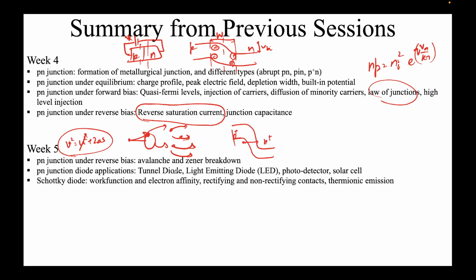And a similar application was the tunnel diode, whose I-V characteristics used to look something like this. First, the current increases due to the band-to-band tunneling. Then the current reduces because the drift in the forward bias has not come into effect yet, and the tunneling has started to reduce. Finally, thereafter, the drift and diffusion mechanism, the typical forward bias, takes over. Then we saw the LED; the photoelectric solar cell will come in the next week or so, and thereafter.